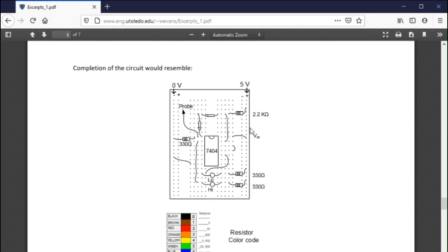And as you make connections, you would say, I'm going to put a resistor in here, and the resistor goes from here to here, and then that jumper's down to here. So you've got a jumper from there to there. You've got a jumper from here to here, and it goes all the way across to that pin. So basically, anything in this row is tied together.